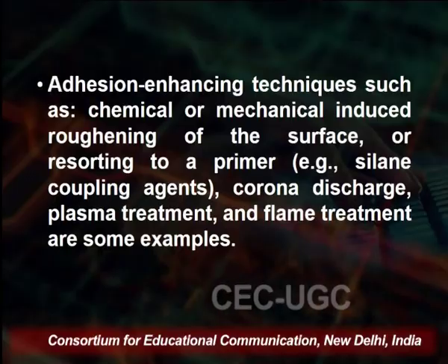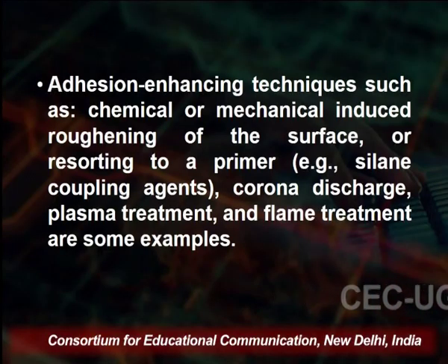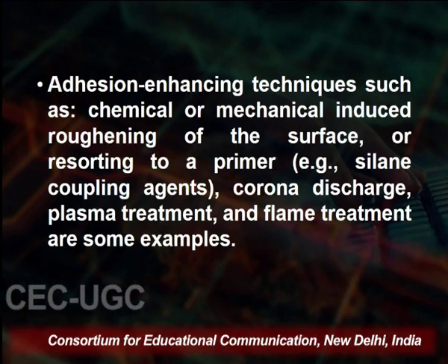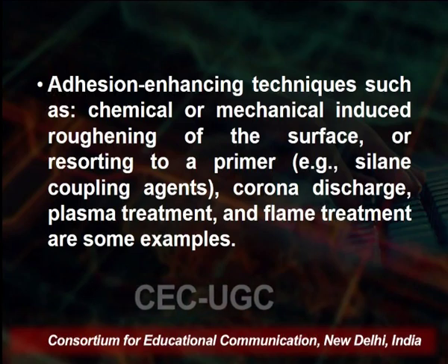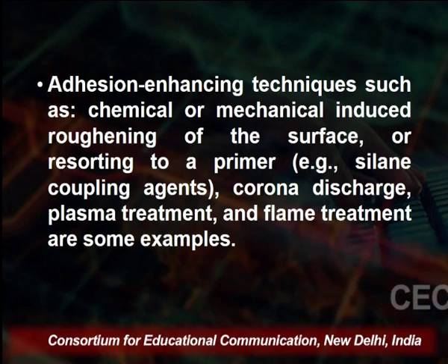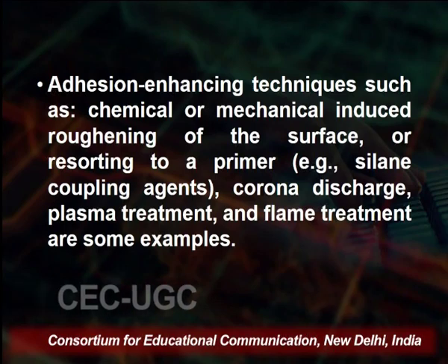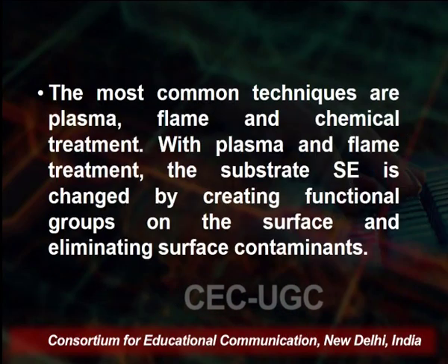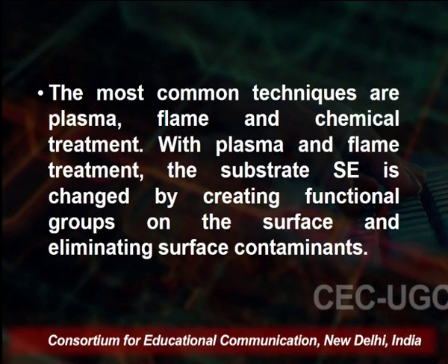But increasing the surface energy is the primary requirement in the polymer substrate. So adhesion can be enhanced by techniques, both chemical as well as mechanical, which induce roughness of the surface, and by applying a primer, or flame treatment. Some examples we have are the most common techniques, like plasma, flame, and chemical treatment.